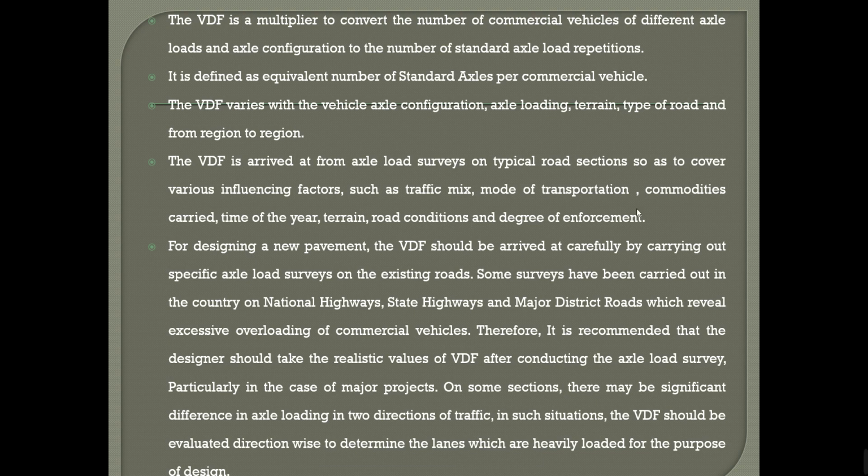In the last class, we were discussing the VDF, which is a multiplier to convert the number of commercial vehicles of different axle loads and axle configurations to the number of standard axle load repetitions.